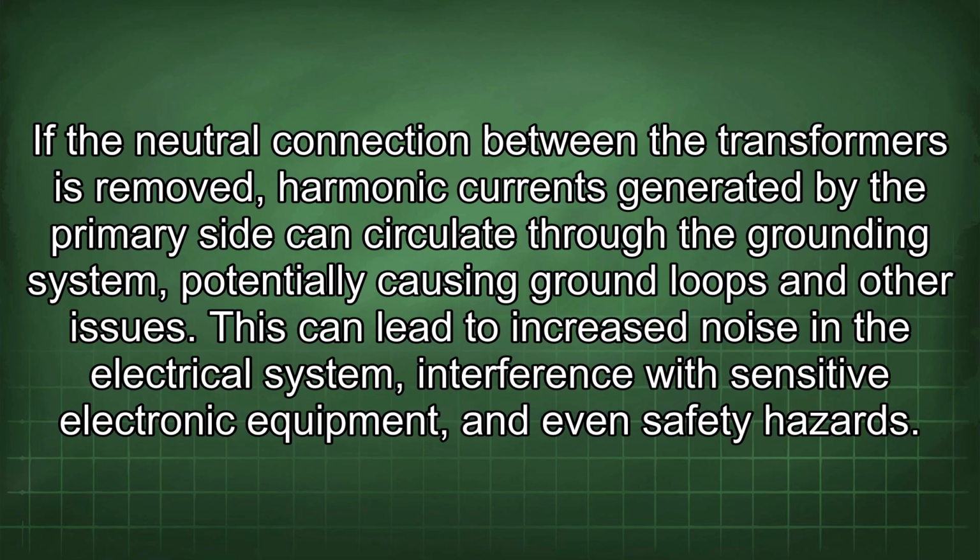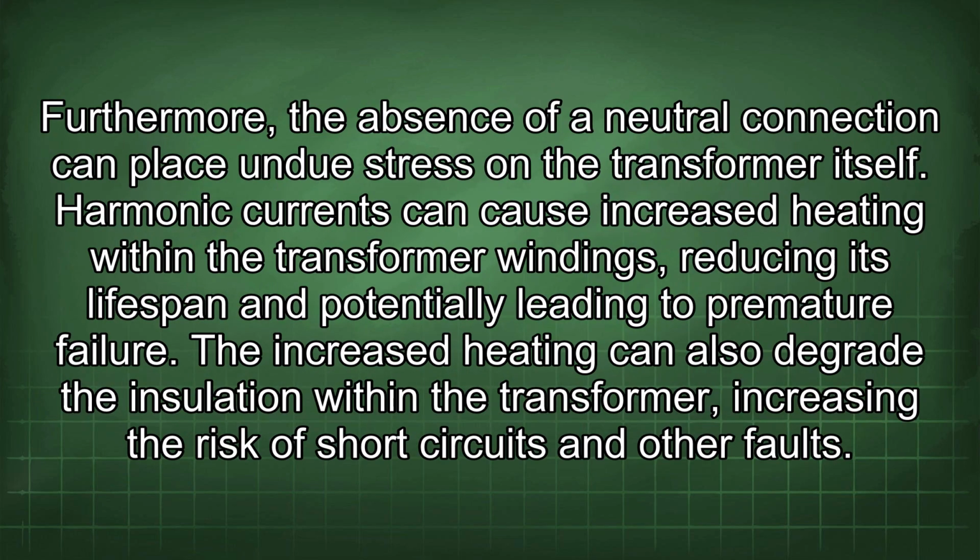This can lead to increased noise in the electrical system, interference with sensitive electronic equipment, and even safety hazards. Furthermore, the absence of a neutral connection can place undue stress on the transformer itself. Harmonic currents can cause increased heating within the transformer windings, reducing its lifespan and potentially leading to premature failure. The increased heating can also degrade the insulation within the transformer, increasing the risk of short circuits and other faults.